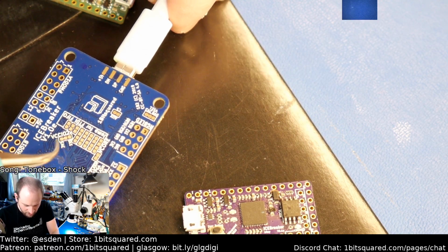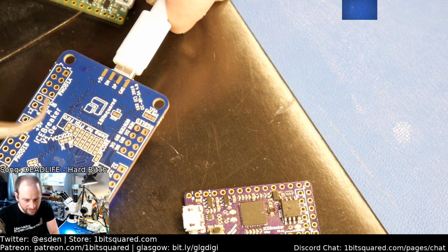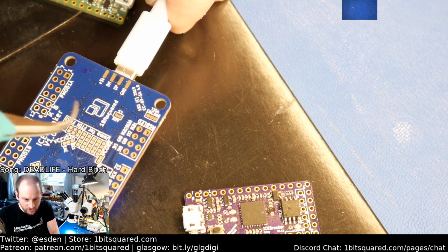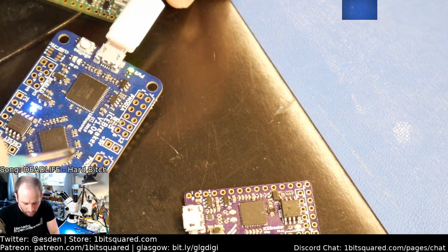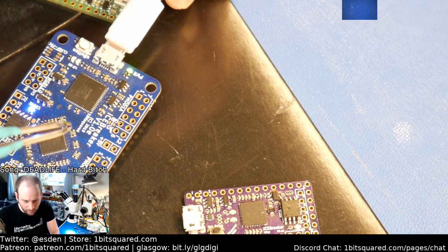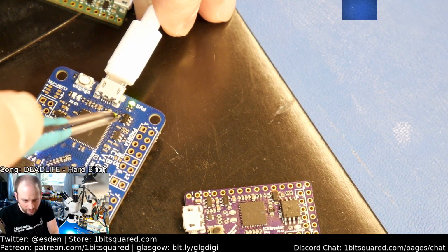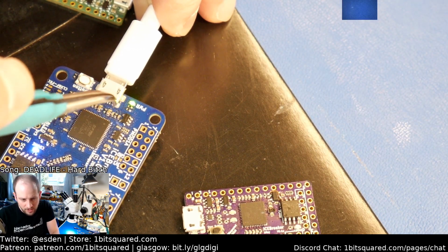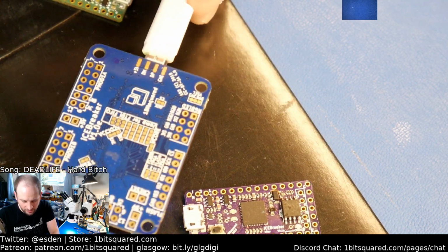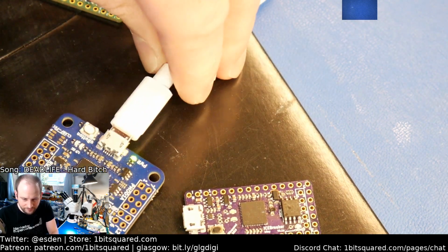It's this selection of the 1.8 volt GPIO. So you can actually switch the GPIO of some of the banks of the FPGA to 1.8 volts, because the FTDI chip has a voltage regulator to 1.8 volts, and we tap into that voltage regulator, and you can swap the bank power supply here.